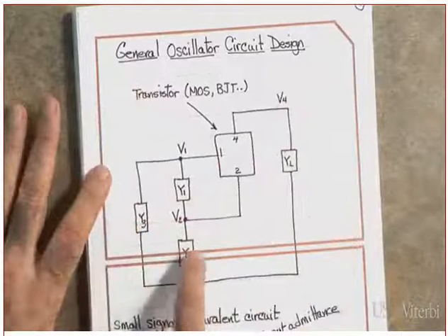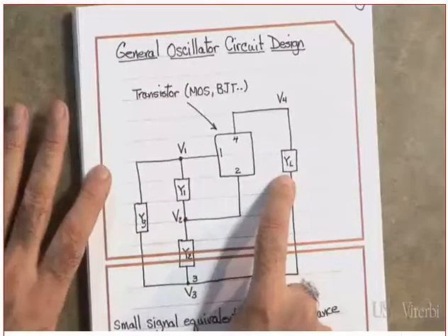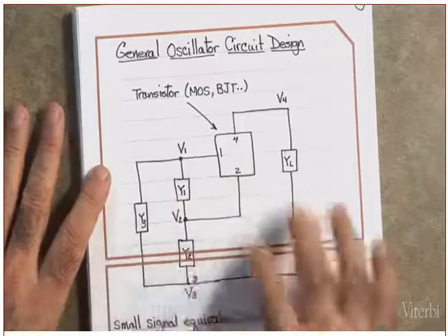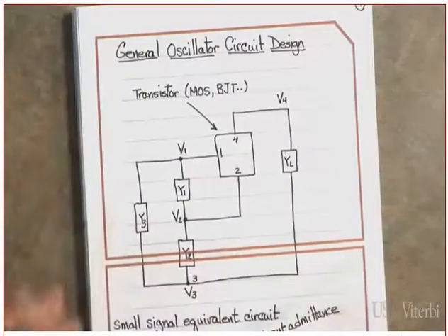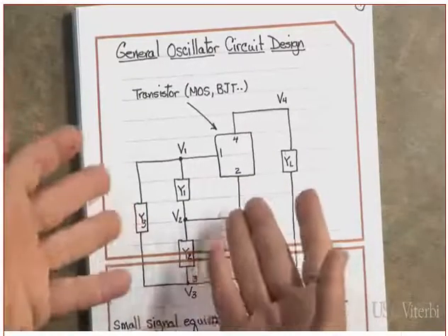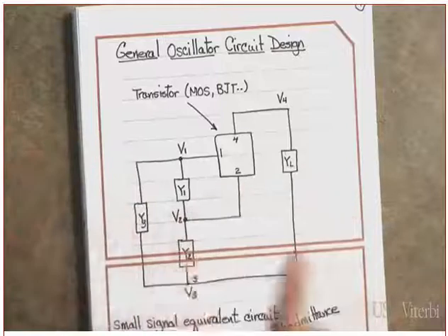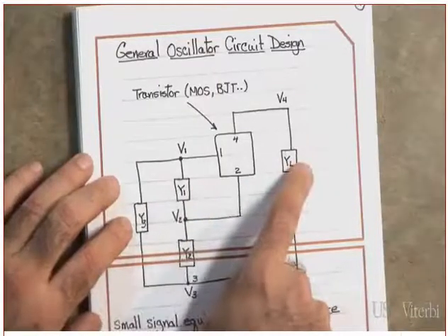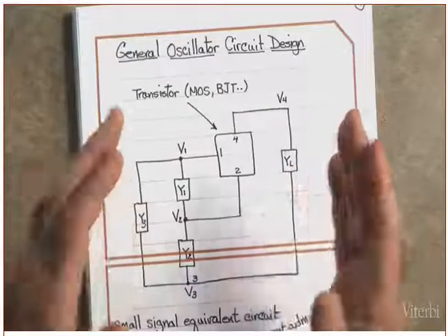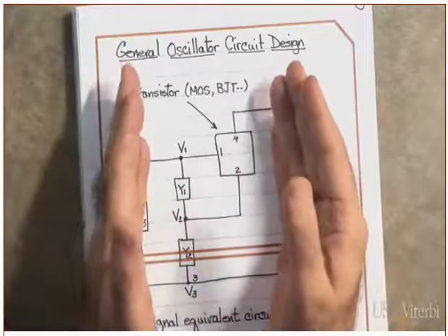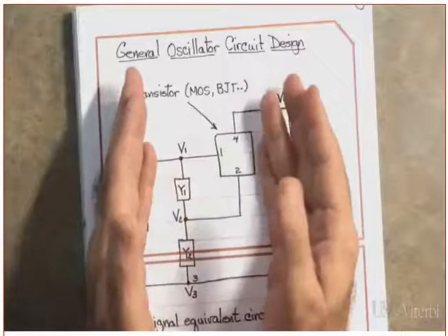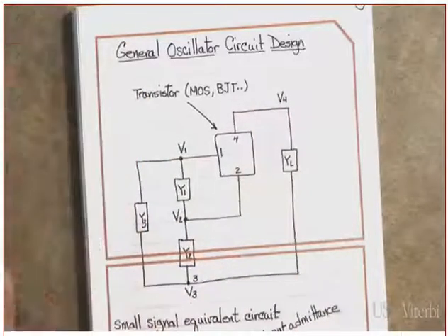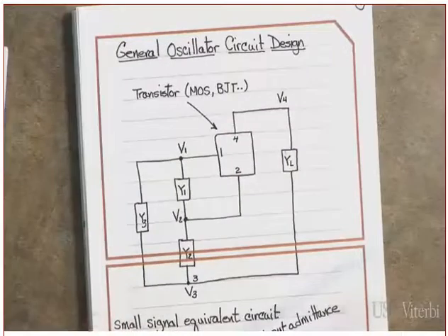You notice, by the way, I did not put components here. I left it in terms of admittances. From the equations, we will see under what conditions this circuit will oscillate, and then I will choose those components accordingly. Did you get my point or not? In other words, this is a general derivation of the oscillator, and then I want you to see one thing before, one second.